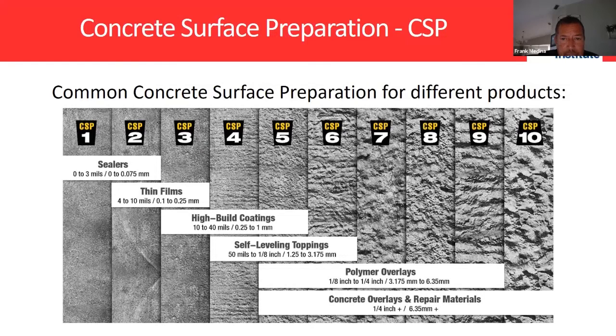But with that said, by doing the scarifying that we did, it caused divots, and the divots are in question about, is that why we're getting the bubbling? So once again, we're waiting for Tremco to come back with an alternative fix for this problem. But, Frank, just thinking about it a little bit, a divot is going to be deeper material, so it's going to be thicker there. So you may have a different cure time within the divot than you do on the top of the high point, so to speak.